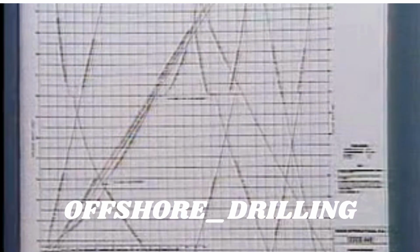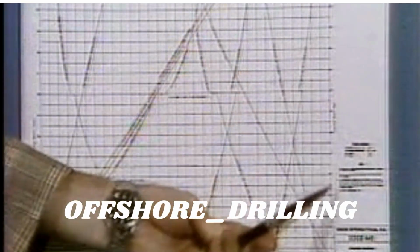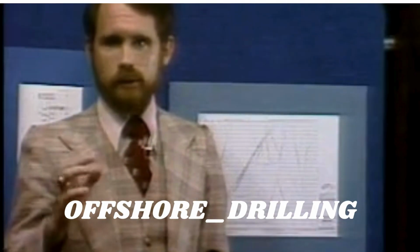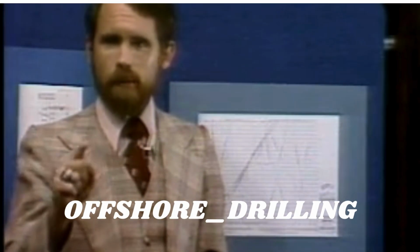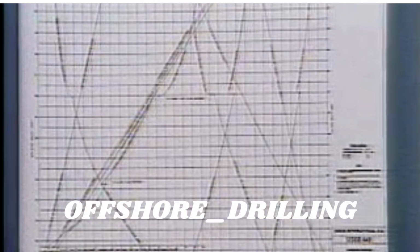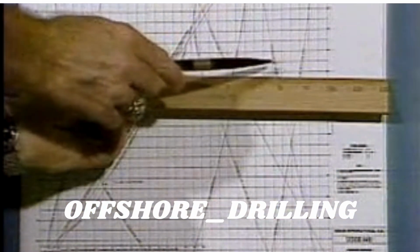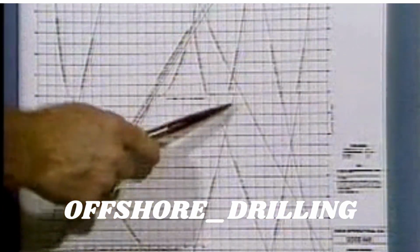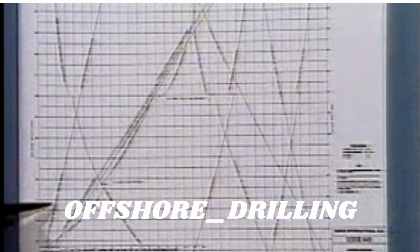Along both sides are draft scales. As with the deadweight scale, we usually enter this graph by first locating the desired draft along the side of the graph. Once we have found that point, we lay a straight edge until it intersects the curve that we are looking for. The graph contains curves for tons per inch immersion, height of longitudinal metacenter, vertical center of buoyancy,